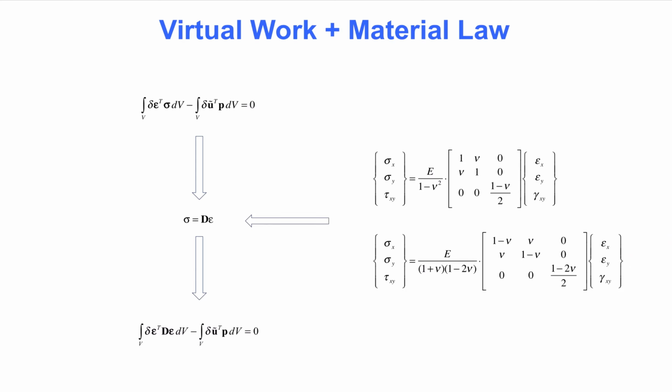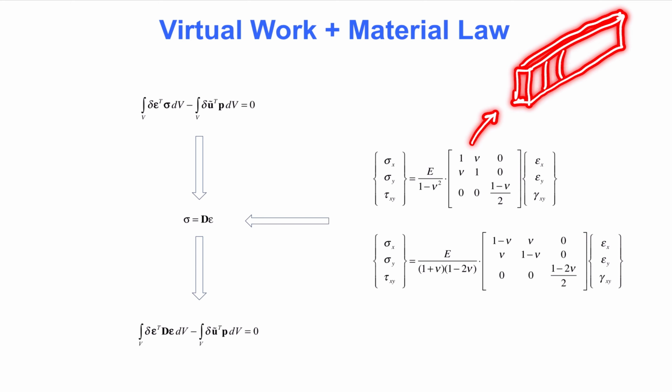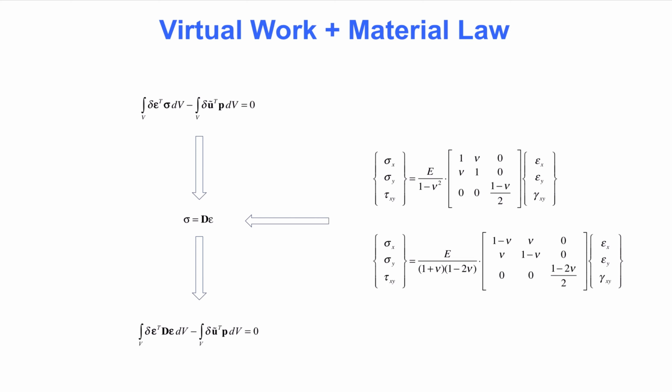Plane stress applies when there are no stresses perpendicular to the considered plane. This applies to relatively thin planar members, such as a wall or a narrow beam that is modeled with two-dimensional continuum elements. Seen from the side, such a beam forms a two-dimensional continuum problem in the xz plane. The plane stress material law is appropriate in this case because there is no stress perpendicular to the sides of the beam. Conversely, plane strain implies that there is zero strain perpendicular to the plane under consideration.